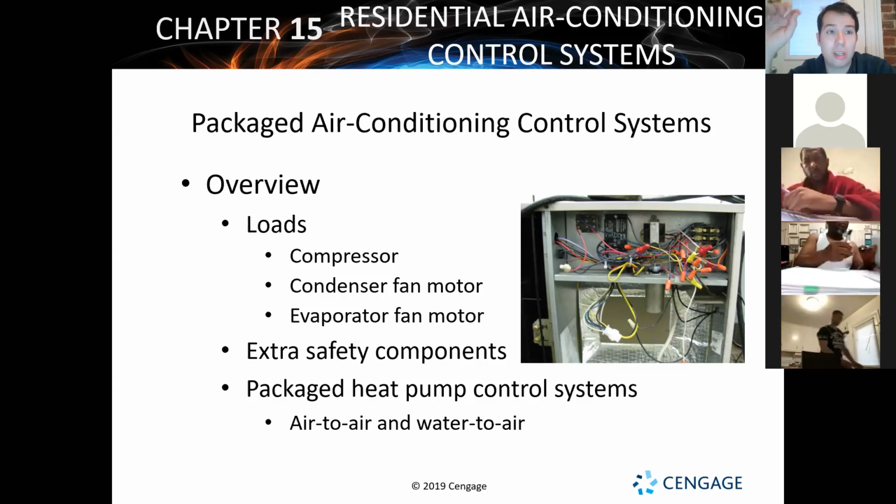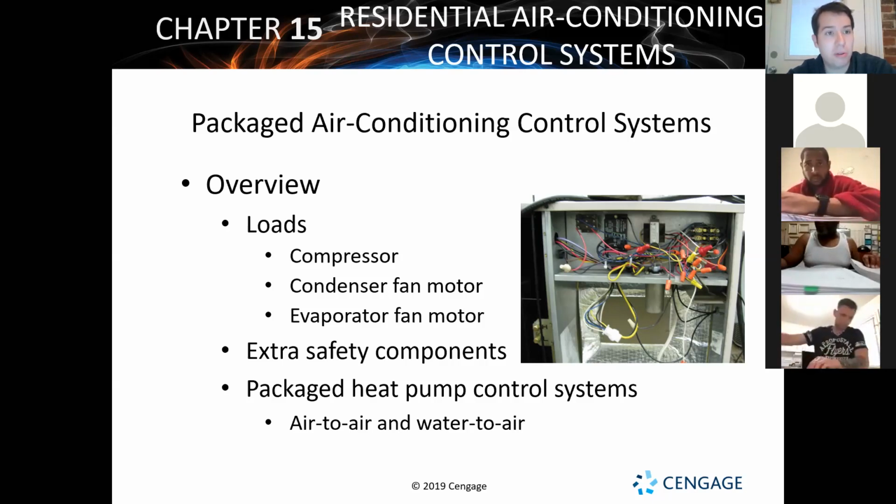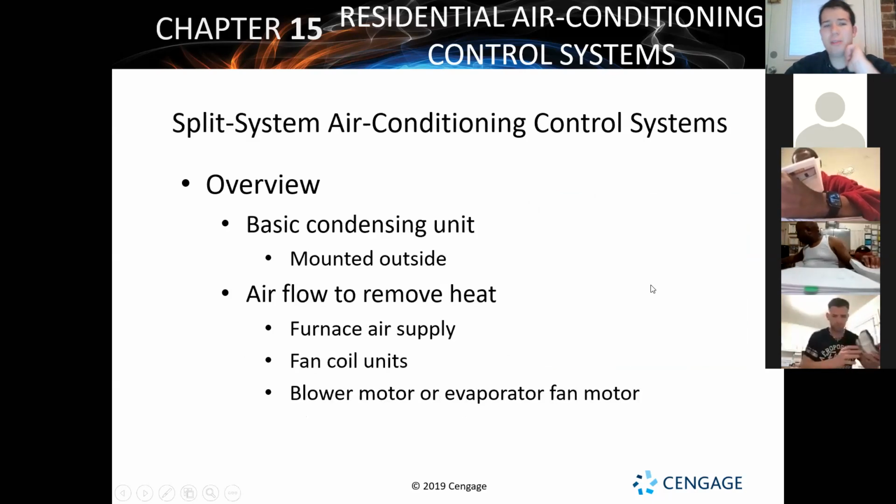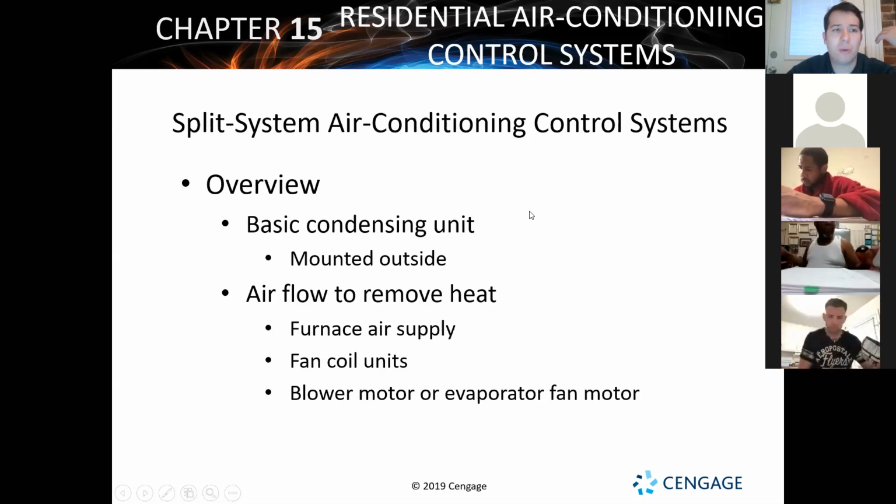Pretty much everything is factory wired. Very little of it is what's called field wiring, where you actually wire it in the field. That's things like your thermostat connections, your 120 or 240 volt connections. Those can all be run off of field wiring. So again, package units are going to have safety components, all sorts of different stuff. It's going to be the same kind of thing you're going to see on a split system nowadays for what kind of safeties will be involved and what kind of components.